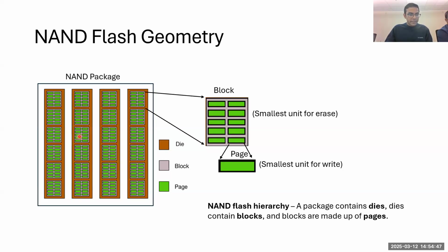So what we do is, as a final step, we move all valid data to a different location, and then we mark this as not available for writes anymore because we don't have any reliability storing data on this block. What that also means is this would reduce the capacity of the drive. So we can notify the host that you probably cannot store 1 terabyte anymore.